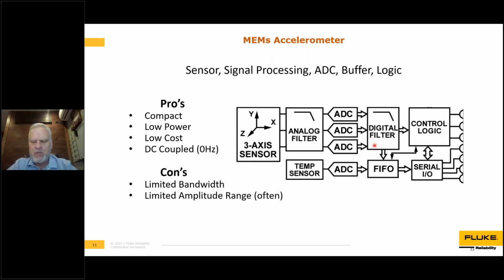A typical piezoelectric accelerometer could measure up to maybe 200 Gs. Maybe the linear range is 100 to 150 Gs, whereas these devices are oftentimes limited to 32 Gs. They can give them higher limits, but then we suffer limited range and limited amplitude dynamic range. So it's the balance of where they're at today.